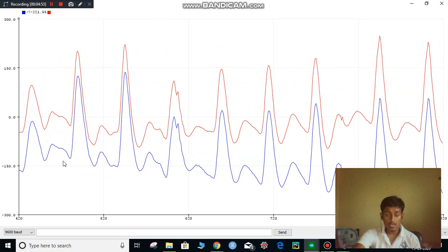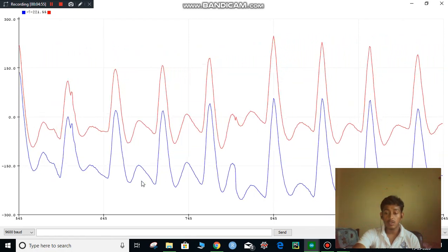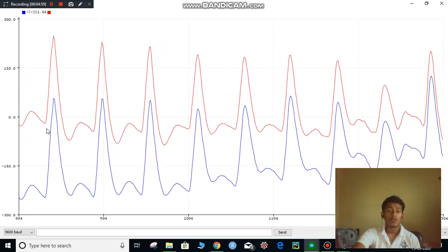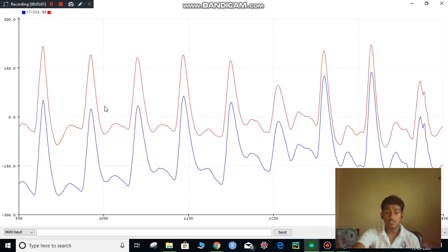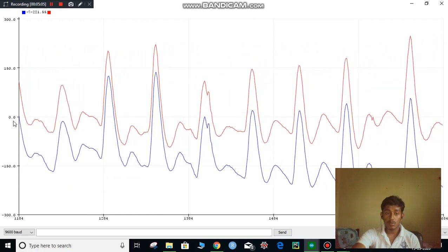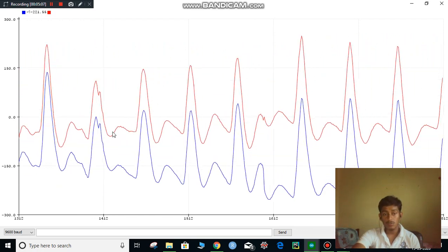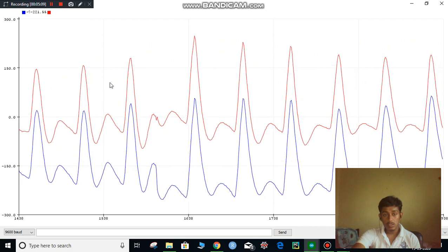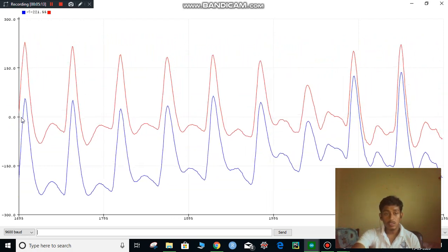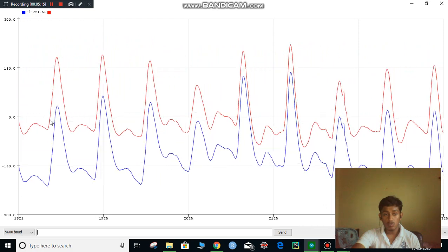So this is a high pass filter. Actually we are removing the very low frequency component. What it's doing, basically, is shifting this time domain signal to make the average 0. As you can see, this red is the new signal, and the mean value of this red signal is almost always equal to 0.